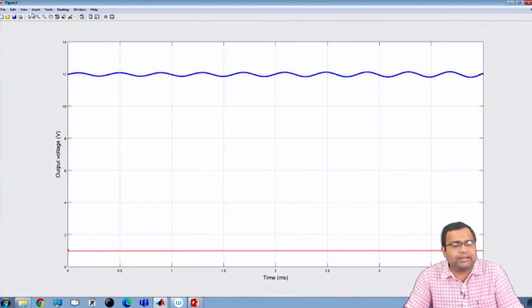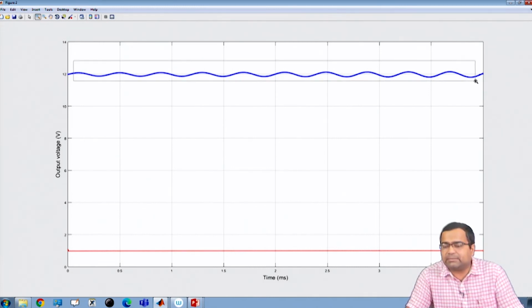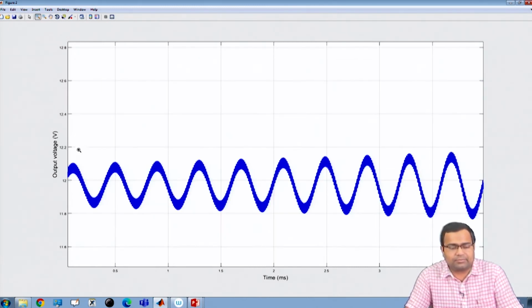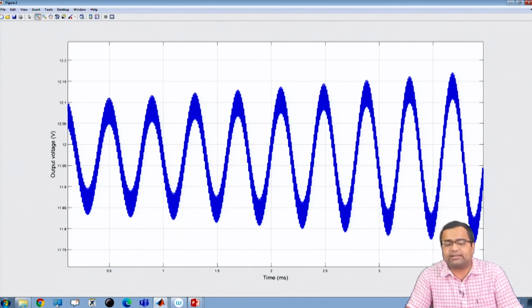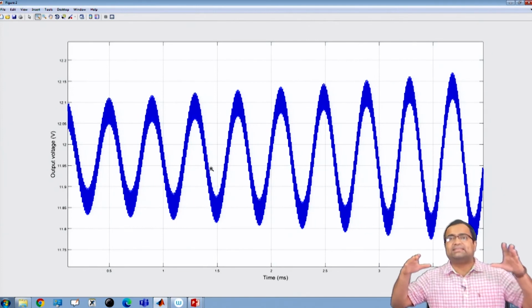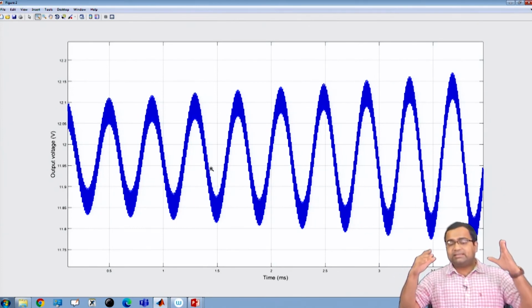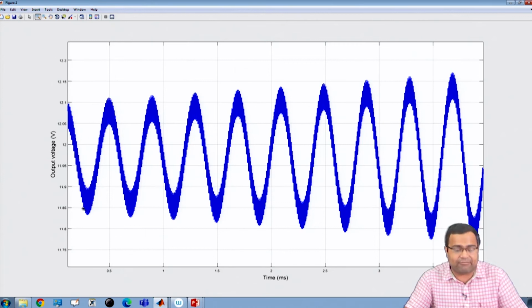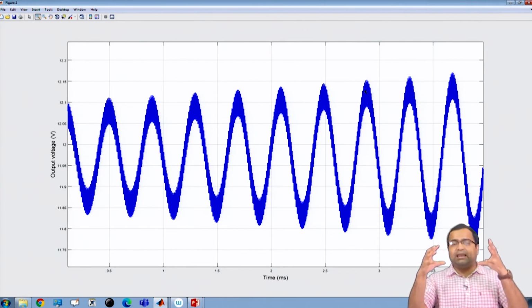We saw that if we reduce the capacitor value, then the stability of the IBC also gets affected. That means now the oscillation is slowly increasing. This is a typical example: if you take the average waveform, which behaves like a linear system phenomenon, and the oscillation is increasing exponentially, this is a typical case for an unstable open loop plant.